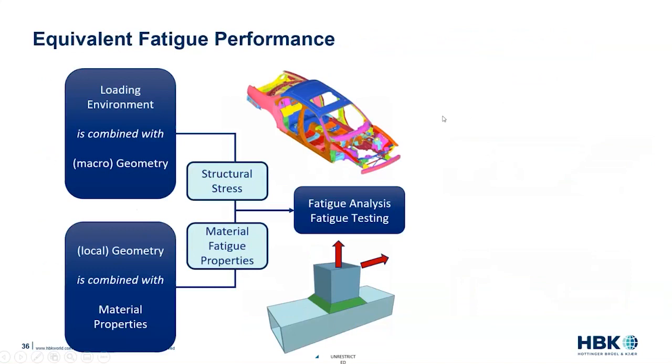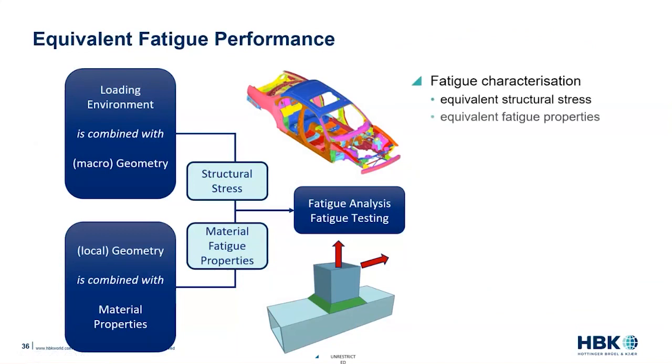So for equivalent fatigue performance between our designed weld specimen and the real structure, we need to have an equivalent structural stress and equivalent fatigue properties to get equivalent fatigue performance.